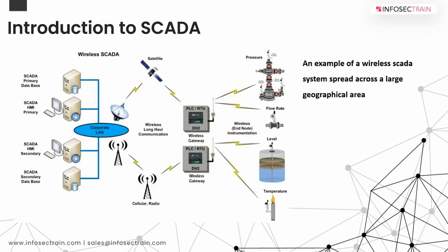So that is that. And only when these live data are available will the SCADA work. Without this, having all the other hardware doesn't make sense. Importantly, the compatibility of this RTU or PLC with the SCADA needs to be verified. That needs to be checked. Not every equipment works with every equipment or application. So again, the applications of SCADA are in all the industries you already know.